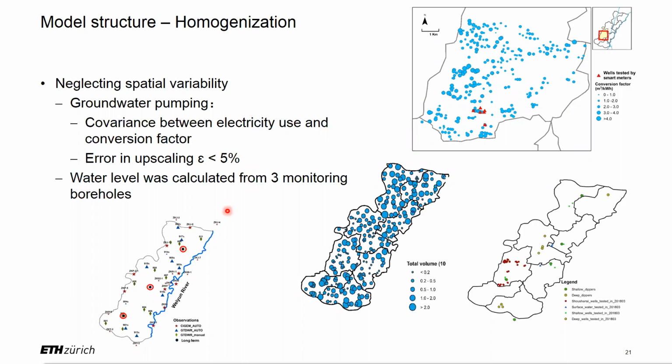For water level, we use the average of 3 long-term monitoring wells located in the north, the middle, and the southern part of Guantao County. By comparing with other short-term monitoring wells, these 3 points can give a representative mean value of groundwater level over Guantao. So neglecting the spatial and temporal variability in the box model is reasonable and acceptable.